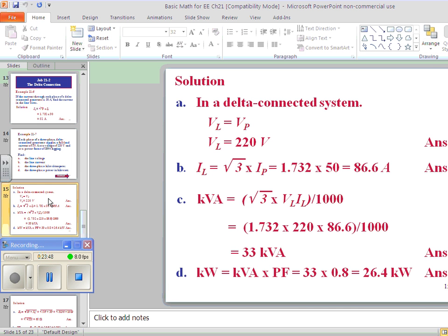correct true power. What is our true power? 41,247. No. You divide. Why did you divide by 0.8? Multiply times 0.8. That's got to be what's wrong, yeah. Okay, multiply.